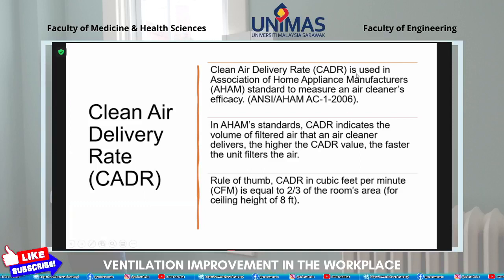Next is, what is clean air delivery rate? The term clean air delivery rate in the SOP that we specify, we do some kind of, not to say modification, but we retranslate the term in the SOP. Instead of using the initial terms from the Association of Home Appliance Manufacturers, what we do is make people understand that clean air delivery rate can be related to the air change per hour. It is basically the flow rate capacity of the air cleaner. It is specified in the standard AHAM AC-1/2006, and the rule of thumb for calculating the clean air delivery rate, or CADR, it is basically